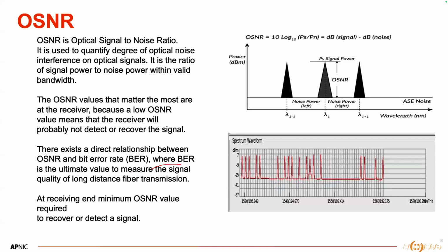You got my point? So in such a case, the negative dispersion fiber we are adding will only add loss, right? Nothing else. Yes. The DCM fiber spool is only adding distance, length, in the network. With distance and length, you are supposed to face a few optical characteristics like non-linearity.